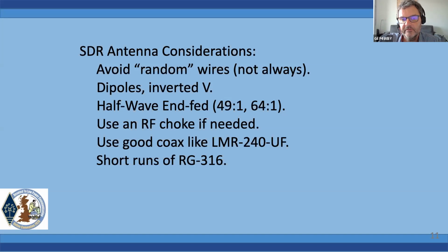In some places, depending on the nature of the ground, it's not going to be a problem. Depending on what's around your antenna, you might have a problem or not. And I have radios and antennas that some days when I pair them, in some places I have problems. So always have an RF choke when you go portable because you don't know when you're going to need it.